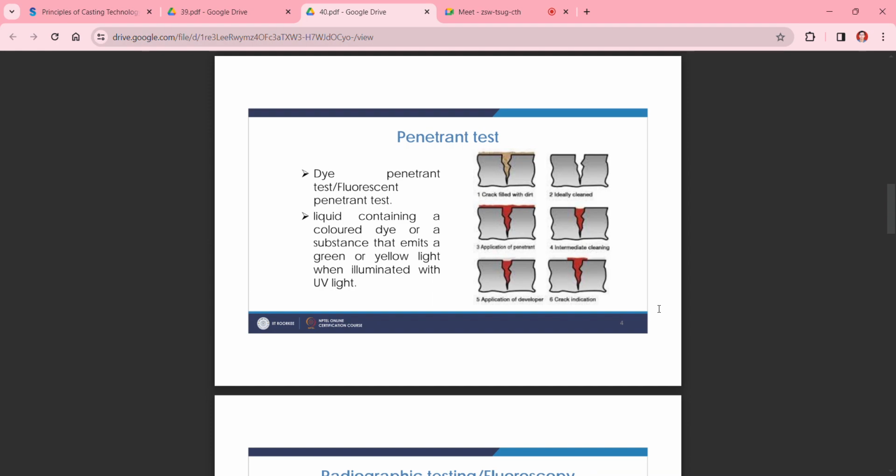After that, that bubble is going to break. If the pressure exceeds the threshold limit, due to that bubble blast your casting is going to get distorted, and that can create major problems.